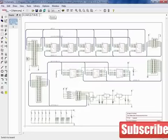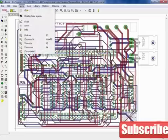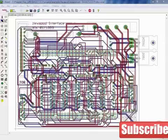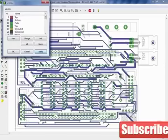We can open the project in board view, which shows us how the circuit is laid out in the actual circuit board form. We can see all the components connected with circuit traces. The red traces are the bottom and the blue traces are the top. This is a two-sided board. We can turn layers on and off. Now we see only the bottom layers.